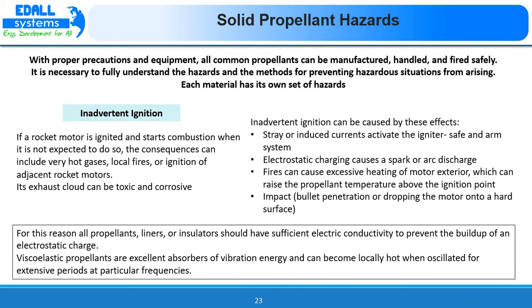So for this reason, all propellant liners or insulators should have sufficient electric conductivity to prevent the buildup of an electrostatic charge. Also, viscoelastic propellants are excellent absorbers of vibration energy and can become locally hot when oscillated for extensive periods at a particular frequency. So this way we can maybe reduce such kinds of ignitions happening at unexpected times.